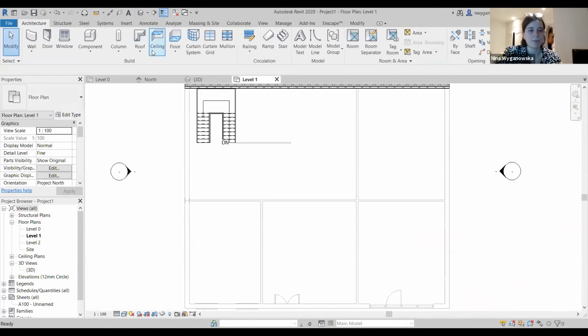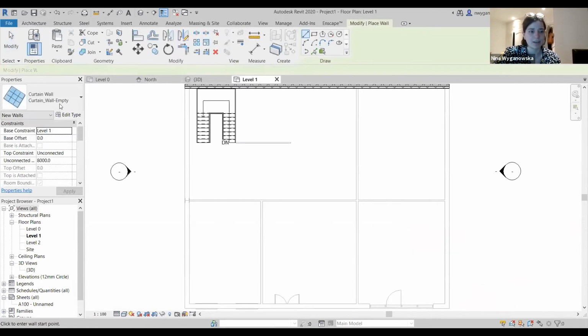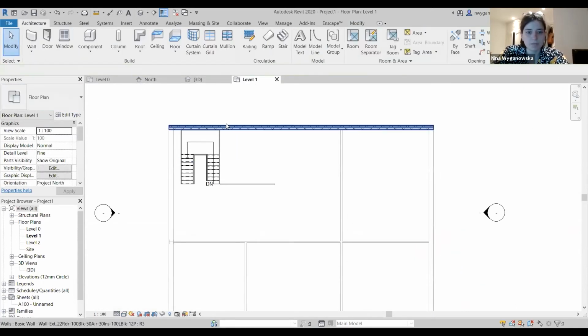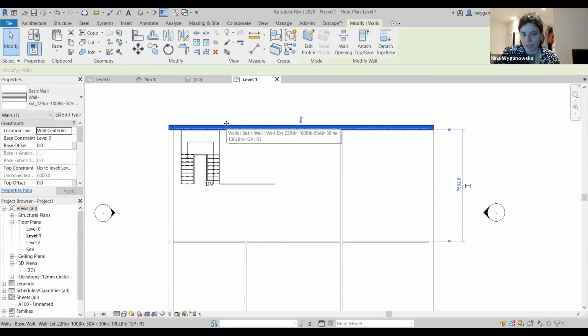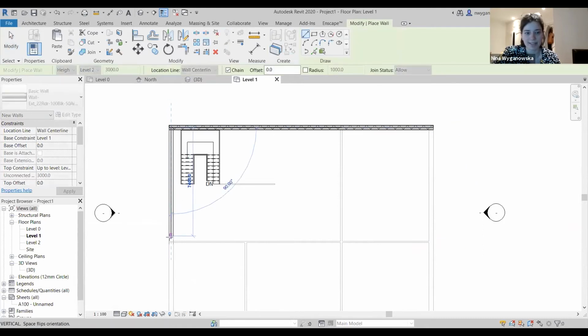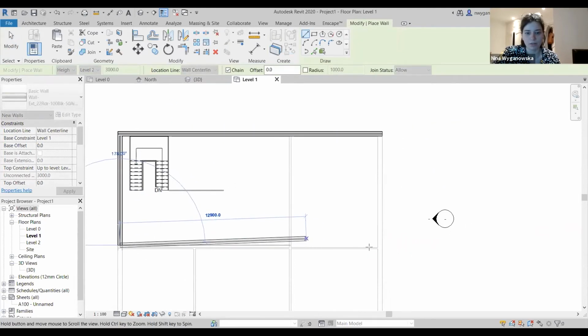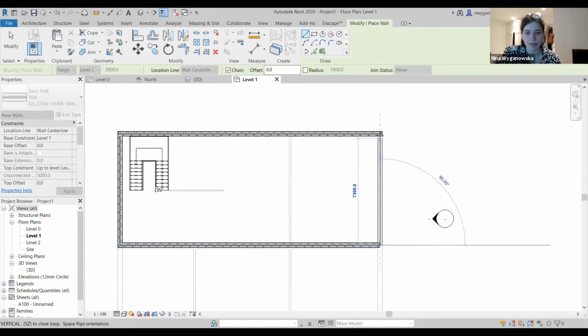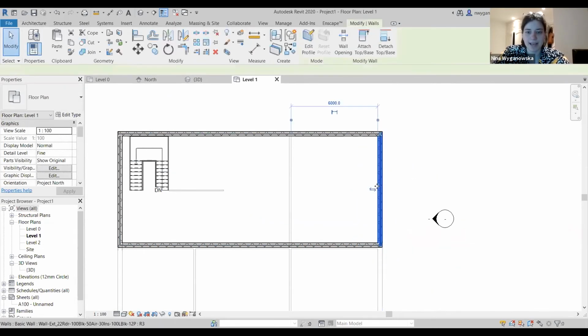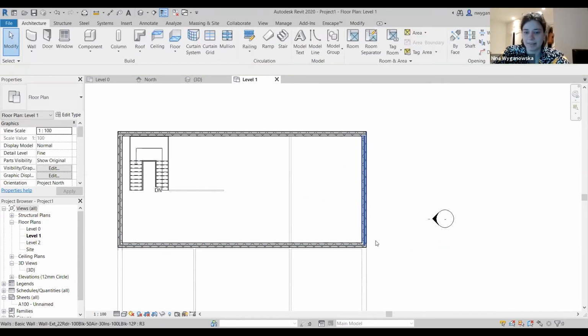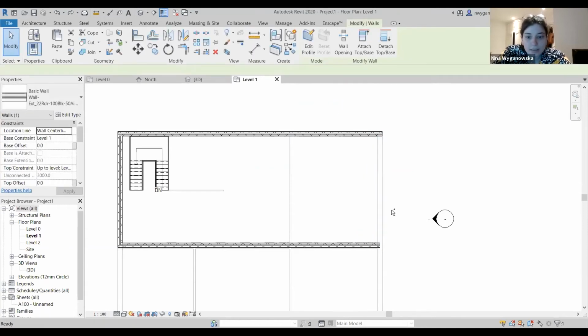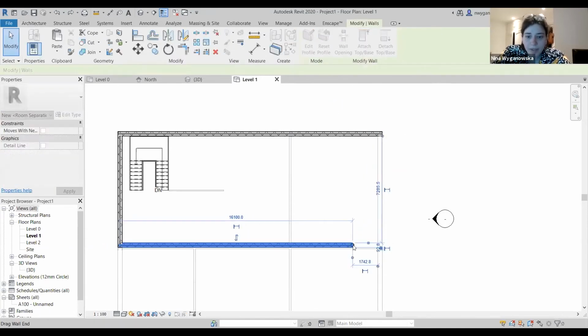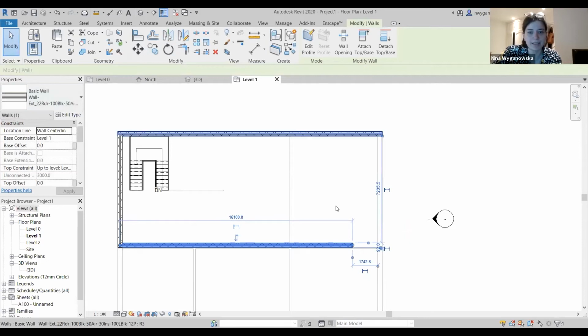And let's say I wanted that second floor to actually have extra walls. I don't want to lose the wall that I've already done, so you can say create similar. That basically allows you to create the same type of wall that you had before. And let's say I didn't properly align this. Sorry, I messed up right now. But let's say if you aligned it, it's fine.